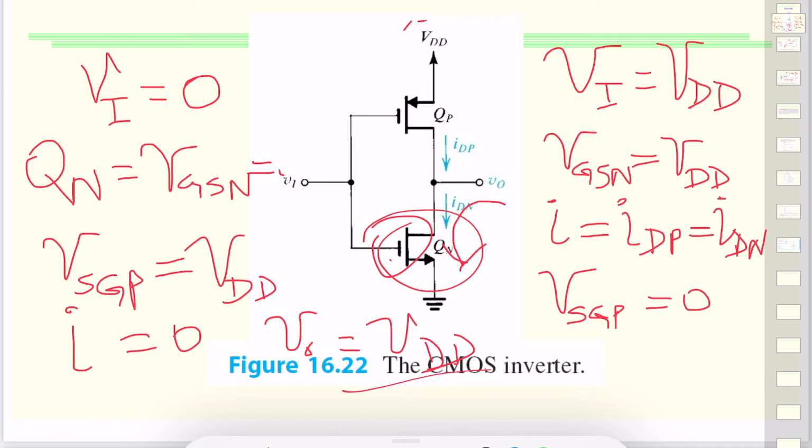So in a similar way, when the input is low, the transistor QP can cause a relatively large load current. Which means it can provide high current and can result in charging, if there is a capacitor on the load, so it can pull the output voltage up and try to bring it towards the power supply. So hence we call them the pull up device. And we have seen this idea.